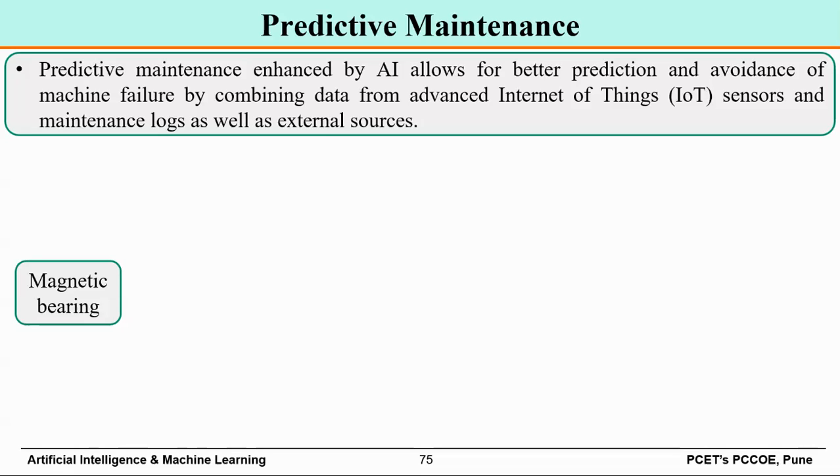Yes. So you change the oil in the two wheeler or four wheeler or in a machine at regular intervals. So is it corrective maintenance or predictive maintenance or preventive maintenance? Preventive. Okay. So that is one example. Another example, bearing lubrication. Is it predictive, corrective? What type of maintenance? Preventive.